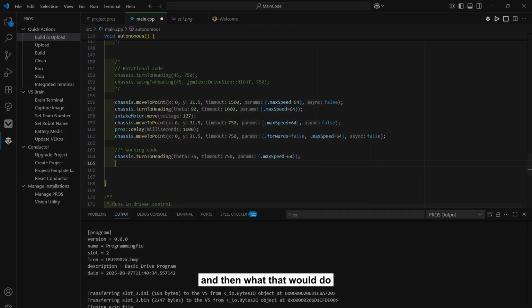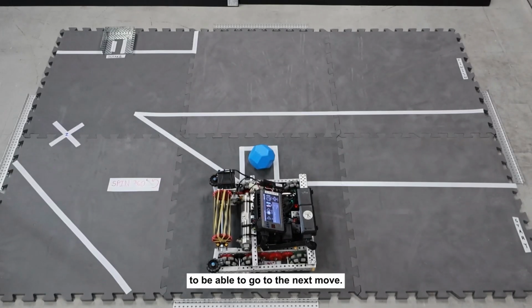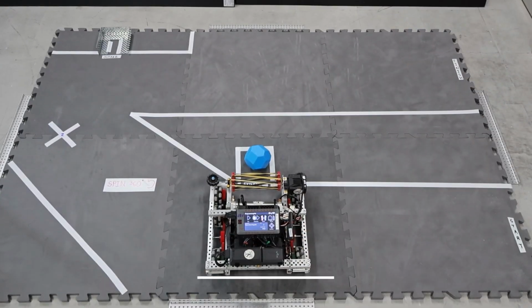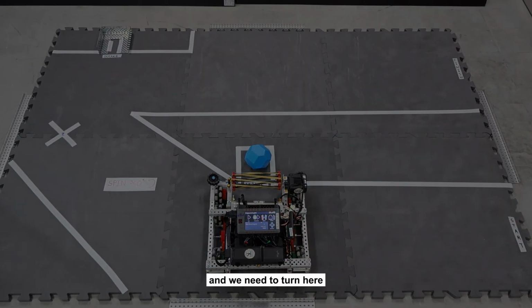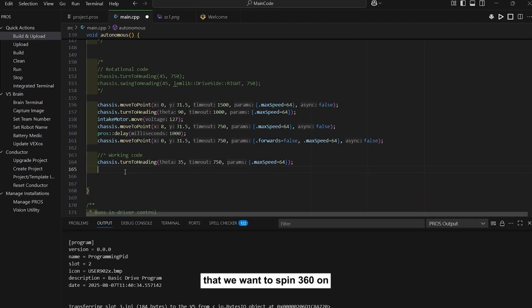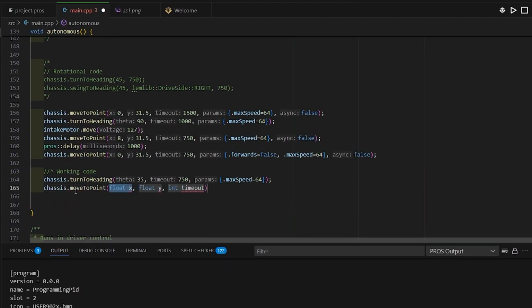And then what that would do is it would basically just turn the bot to be able to go to the next move. So we would be here right now from the end of the last code, and we need to turn here. So once we've turned, we can actually move to the point that we want to spin 360 on. So chassis dot move to point, and then our point is x10 y50.